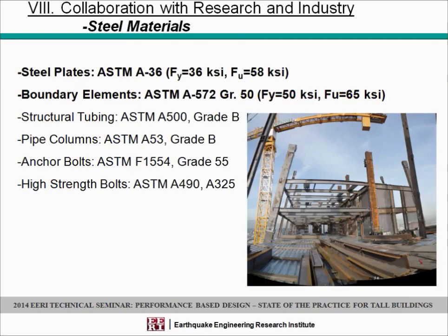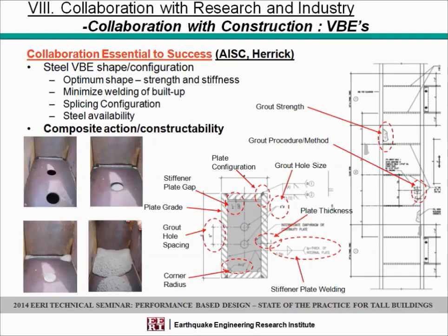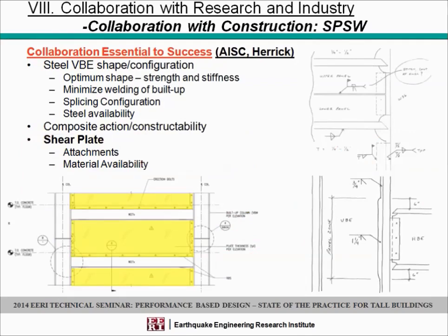I have just a few slides on the construction aspects of it. Collaboration is essential. This is from Herrick, the steel industry, being partners in where you're going to acquire the plates, what's available, cost, how you're going to configure your box columns, the grouted box columns, and holes to allow for the grouting of the concrete, inspection. This shows the holes that were allowed in the continuity diaphragm to allow the grouting of the columns to create the composite effects. It's very essential.